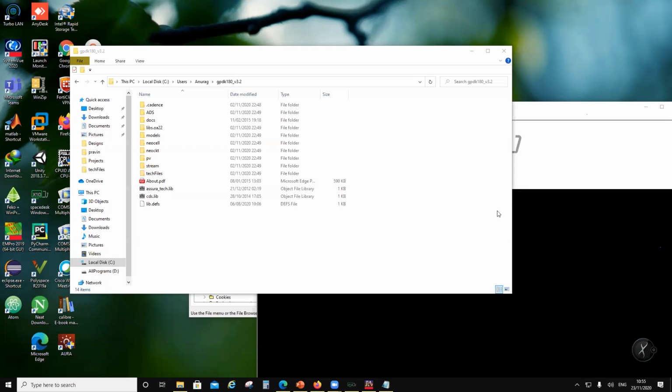So passives are simulated along with the actives. Passives are simulated in EM simulation because EM simulation is a Laplacian solver, and then actives are modeled in circuit simulation. So actives are models; they are not the actual devices. Now, if you want to do both in one simulator, it is going to be very elaborate.